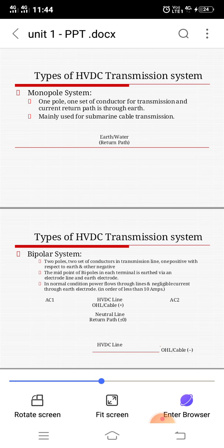Then bipolar system transmission. This bipolar system has two conductors, one positive and the other negative. Each may be a double conductor in high voltage direct current lines. Each terminal has two sets of converters of identical ratings in series on the DC side. Then the junction between the two sets of converters is grounded at one or both ends. Normally, both poles operate at equal current and hence there is zero ground current flowing under these conditions in these bipolar conditions.